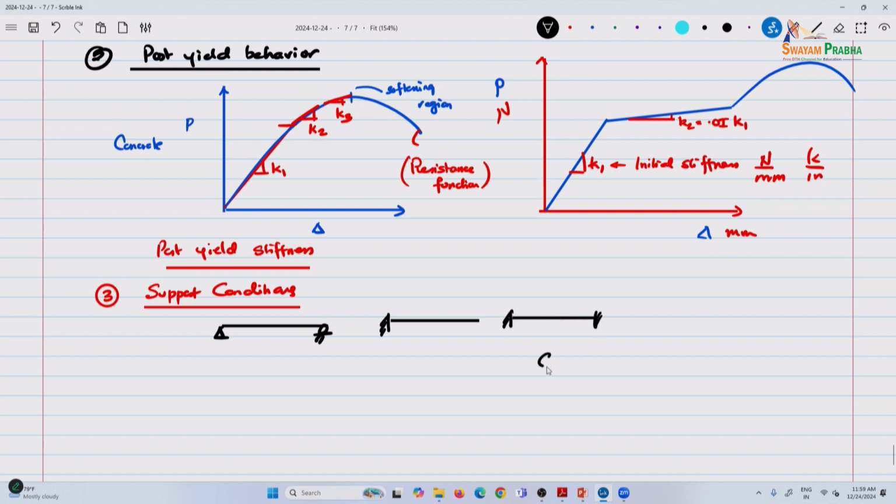If you are modeling concrete elements, or steel elements, for example a steel beam, or precast pre-stressed, or a bridge type analysis, then you might go for simply supported conditions, whereas for concrete you are definitely going to use fixed or cantilever type arrangements or other types of conditions. You have to decide based on what you have as to what type of support conditions is ideal, because your response is going to depend on the support conditions.